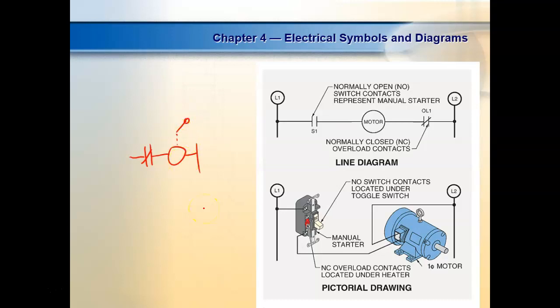So every time the relay would energize, it would open the contact, it would drop out, then it would just sit there and vibrate. Somebody's going to do that in this class, by the way, not on purpose. Especially when we get into reversers, then you have to connect two relays together, and you have to monitor them. Somebody in this class is going to hook it up backwards, and as soon as they hit the start, it's going to go brrr, and it's going to be just like an old doorbell.